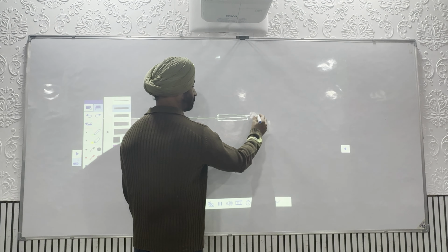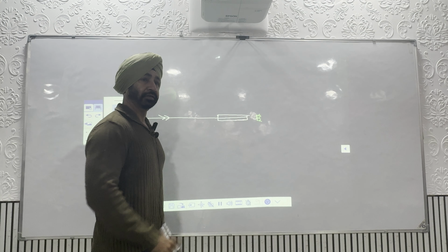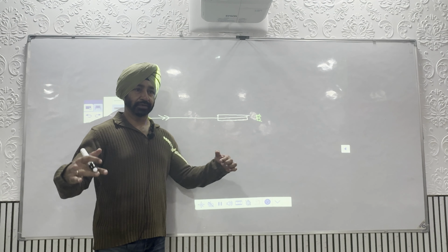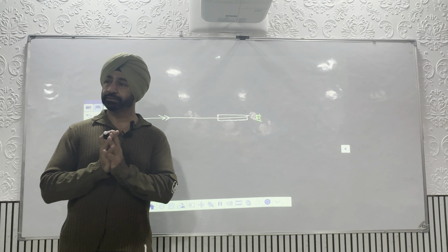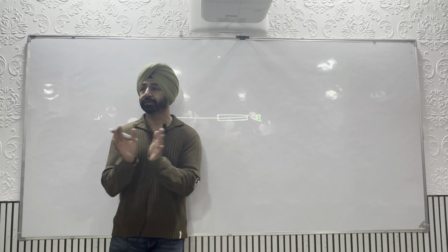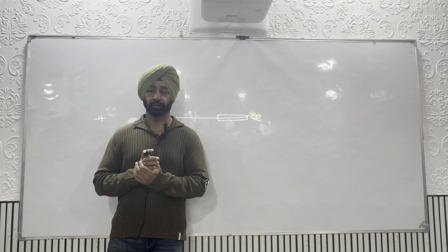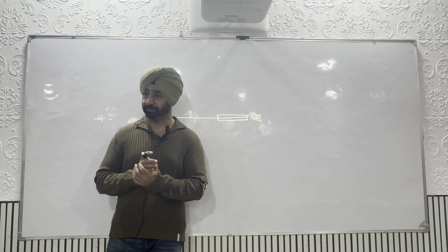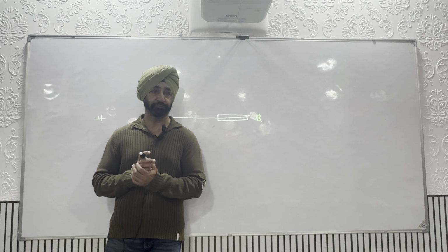Here, you saw those antenna arrays on this side. What distance, we will see in the layout later. But you saw that antenna? Now that antenna is a directional antenna which transmits only in the approach direction. It transmits two lobes of different frequency. Remember what we saw, 108 to 112, it is a carrier frequency, it is not the information.